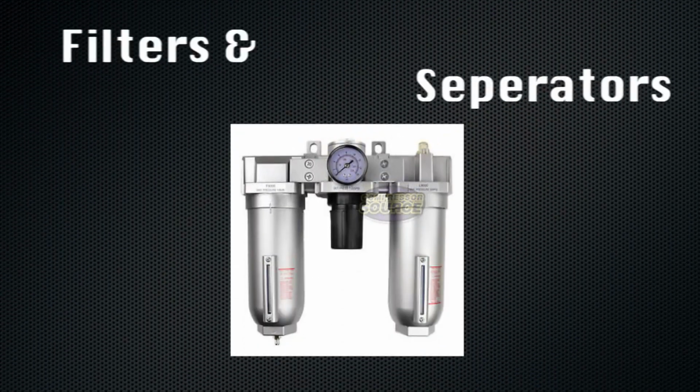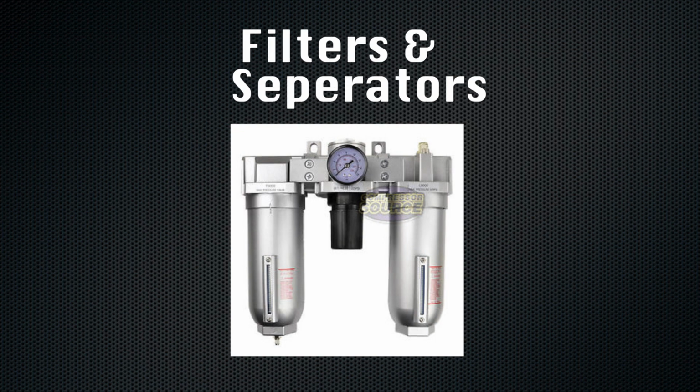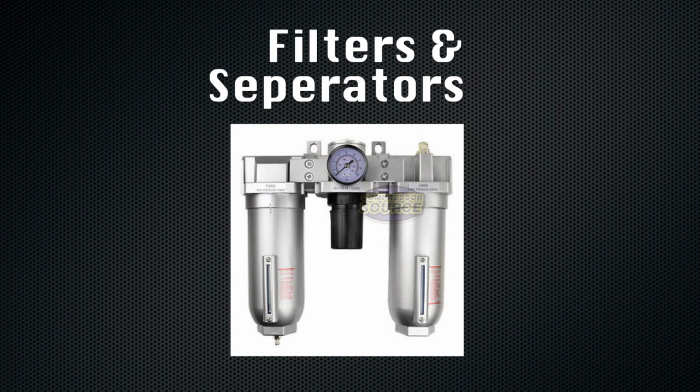Well, that's it for the big pieces in the compressor room. Let's move on to filters and separators. If we ignore them, we can lose the performance we've gained by doing a lot of other tricks. First, a couple points about filters. They're going to occur before and after the air compressor, after the dryers, and perhaps after the separators. So there's lots of filters.